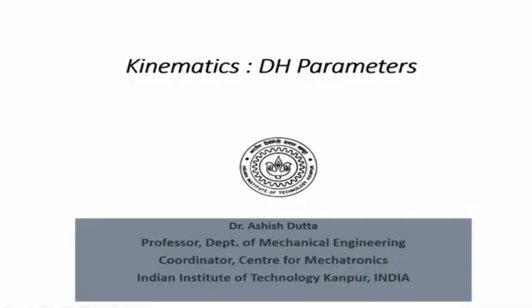Okay. So today's class is about kinematics and DH parameters. Now we had studied in the last couple of classes that in a serial arm linkage we have links which are connected by joints. Joints can be revolute joints, or they can be prismatic joints, and each of these joints has 1 degree of freedom, and they have an axis about which they can translate or they can rotate.